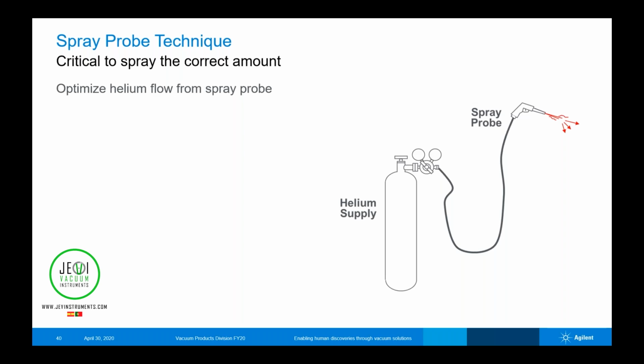A couple other tips on helium and how to use it. You want to make sure you optimize the flow of helium from your spray probe. If you stick your spray probe into a glass of water, you just want to see a couple of bubbles a second coming out of that probe. You don't want to hear that helium coming out. If it sounds like a compressed air line, you're spraying way too much helium.